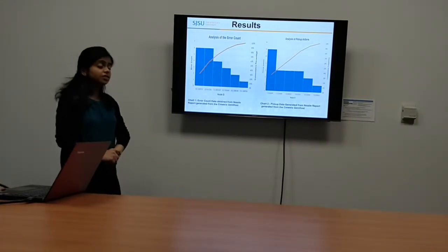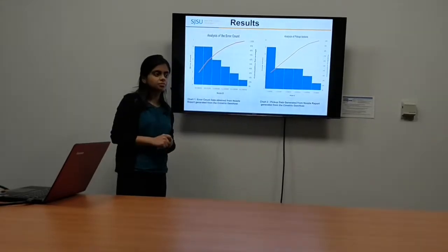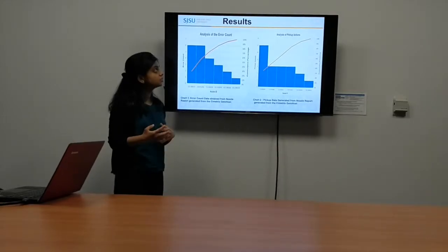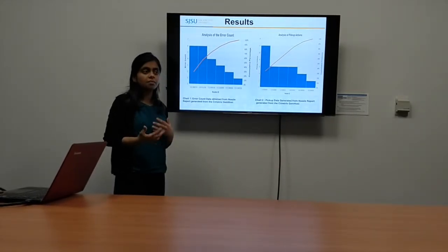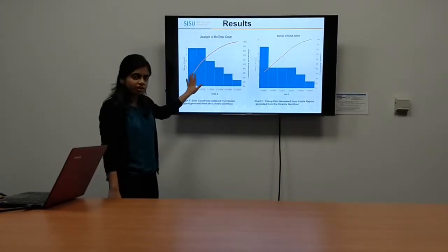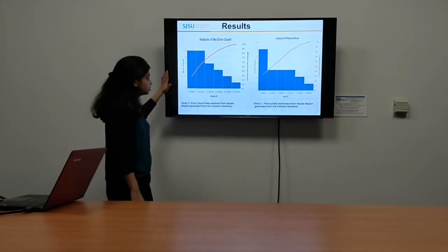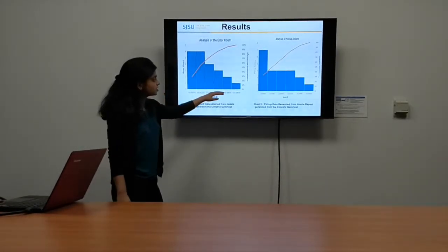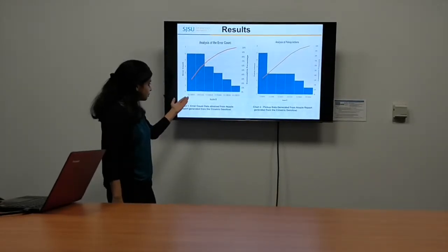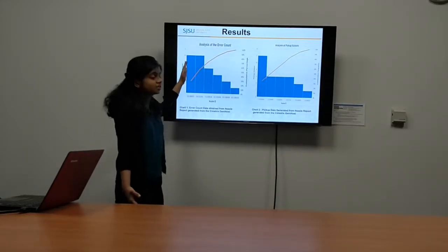Some of the things that we can do in the future, because this is not all that we can do, since SEMI GEM gives you a huge data repository. From a manufacturing point of view, you can make a Pareto chart, like we did in our case, for the error counts of the nozzle usage. While comparing the 6 nozzles that we used in our production, we figured out, for example, that S11-08555 had the highest error count.